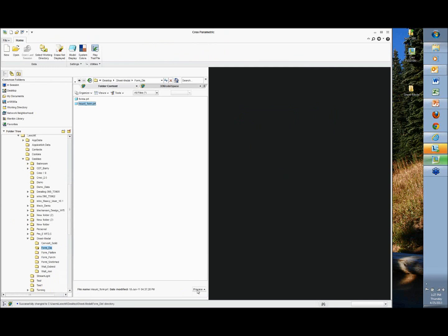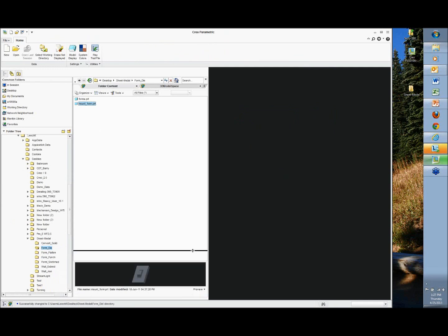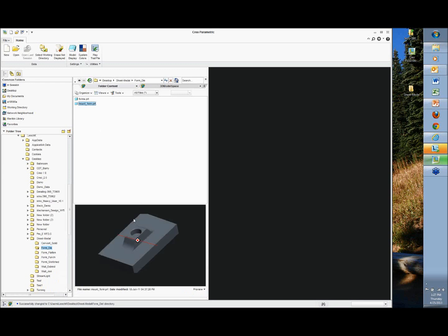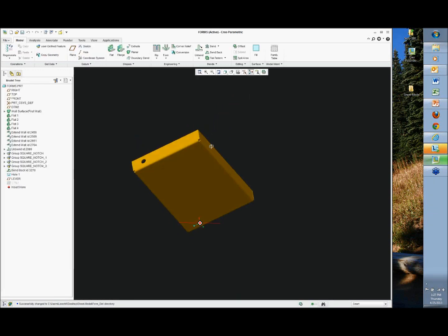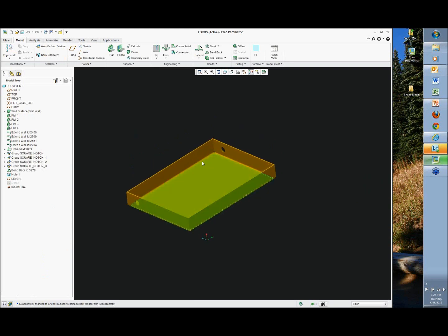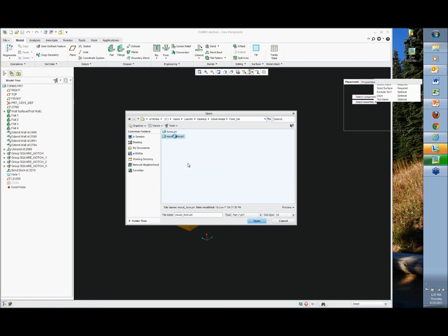Right, we're going to put this in as a die. So this was the old way of doing this. You had a ProE die of this. Still works fine. We want to put that die and press it in place. We're going to go up to form, pick die, it opens up and I got two choices here. One is reference the part, which means it updates if the part changes. We're going to do reference so I can make a change to show you. Or copy the whole part in, where that way I don't need to worry about the library. It will just stay within my part.